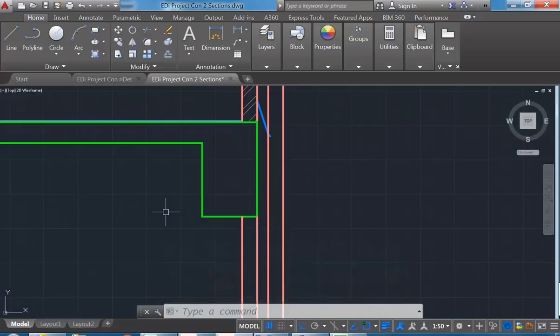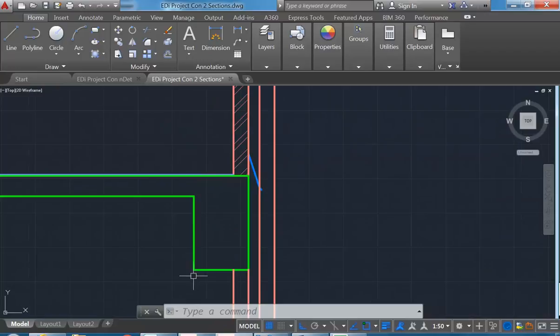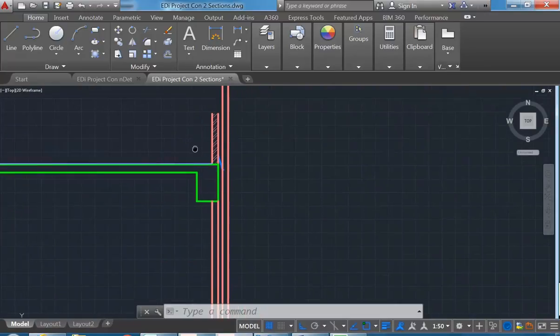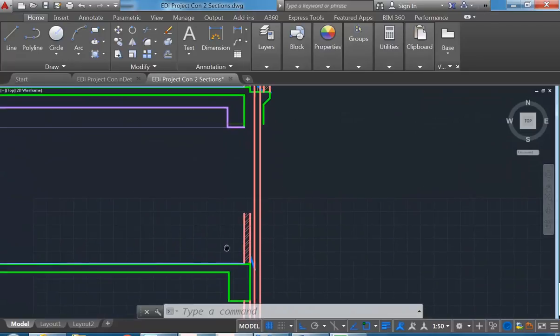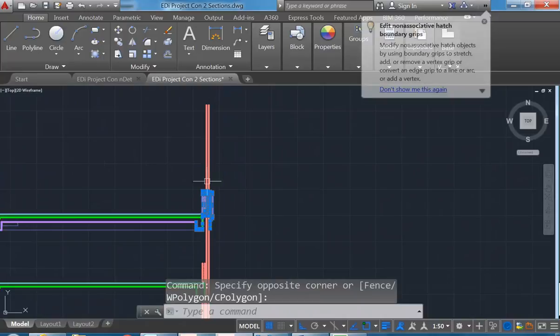That's a standard detail for interiors that you need to know, because all upper level floors will be supported in this way if it's concrete. So the wall is supported on the inner skin of brickwork, and the outer skin of brickwork runs past it. Okay, so that's the way it needs to be drawn, and then it's going to be the same on the level above. So all of these can go,